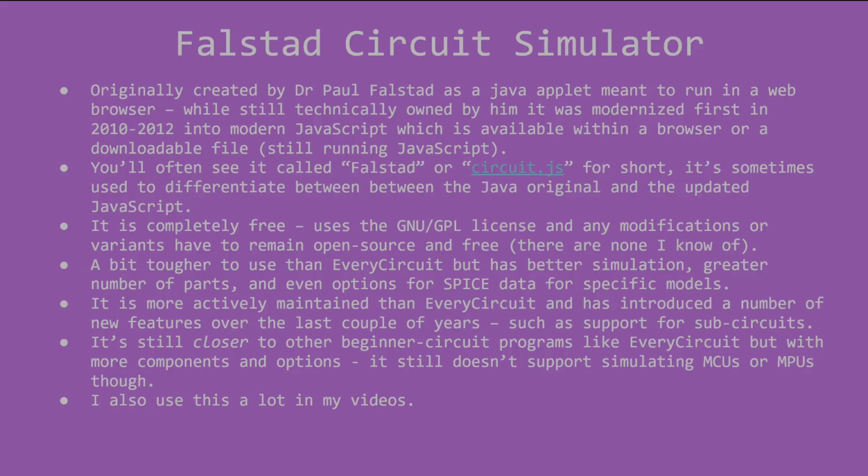It's still closer to something like Every Circuit compared to LTspice, and there are a lot of things it can't simulate, like microcontrollers, dev boards, or microprocessors, although it does have a far greater range of ICs. I do also use this a lot in my videos, so many of my circuits will probably be shown in Every Circuit when possible, and Falstad also when possible.